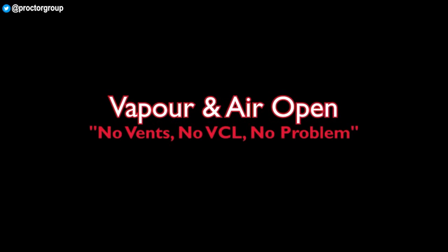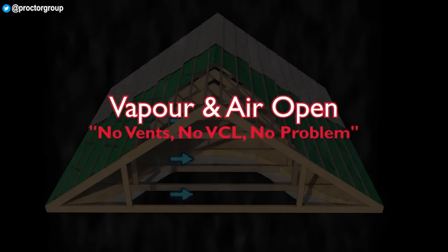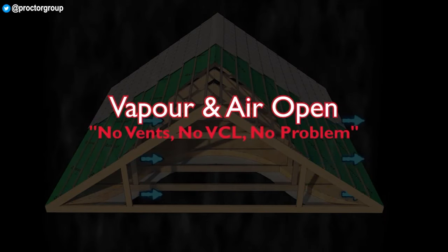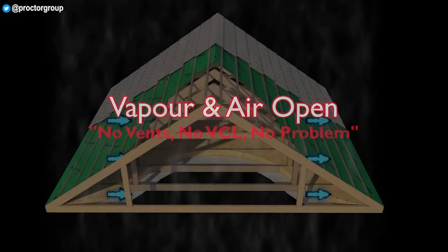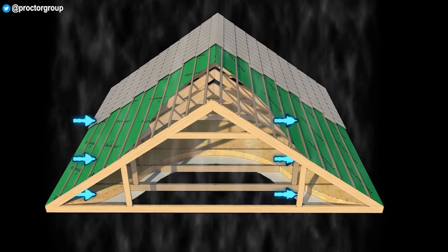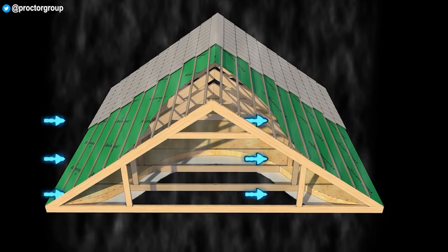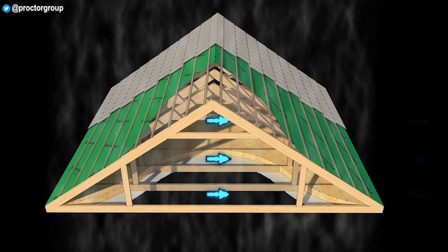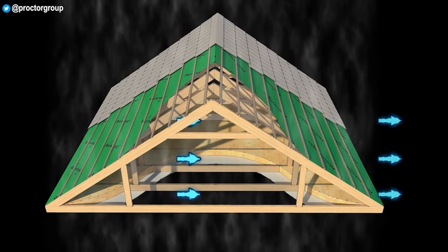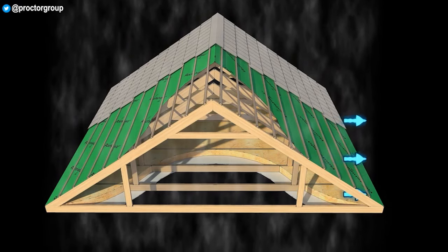Type LR underlay, air permeable. By providing, to quote the BBA, a significant additional mechanism for water vapour egress by convection, air permeable membranes such as our roof shield can always be used with no additional ventilation, as both air and vapour can move freely throughout the entire roof surface.